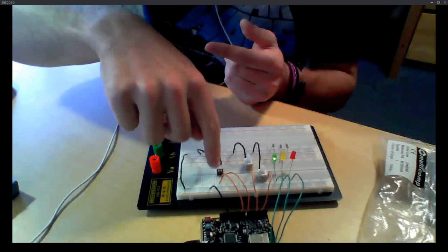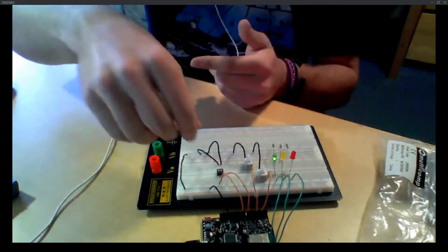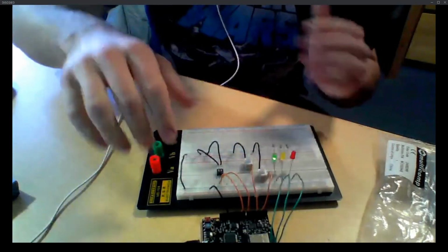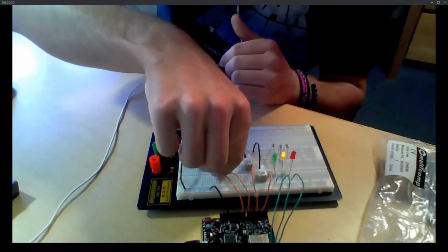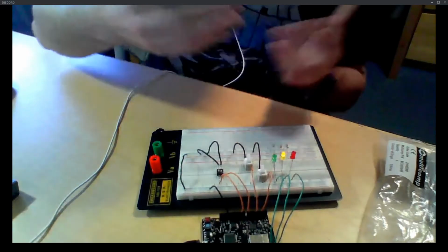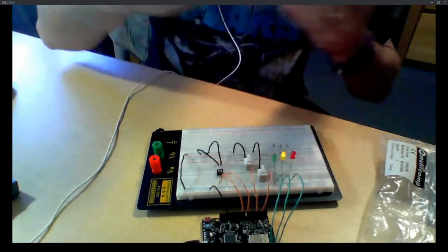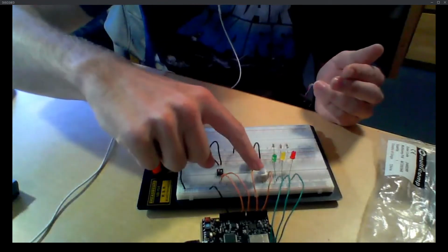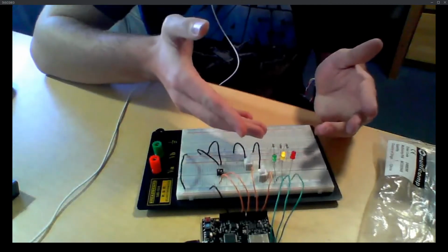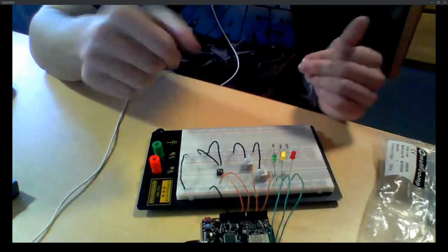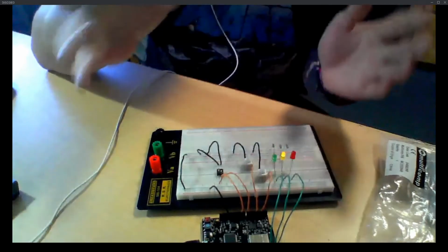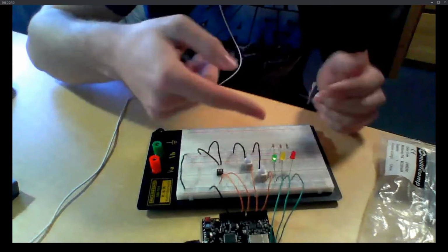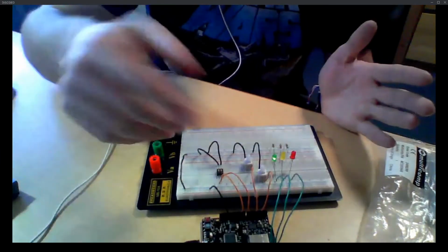And then we have a switch here. It has 2 switches on it. Switch 1, for simplicity, was FLA. So while nothing's happening, if FLA occurs, our green light turns off and the yellow light starts flashing. Now, if I'm at the control panel and I see this yellow light flashing, I'm going to acknowledge that. So I press the acknowledge button, and it becomes a solid yellow light. And then if it's no longer FLA, it drops back down to green, and everything's okay.